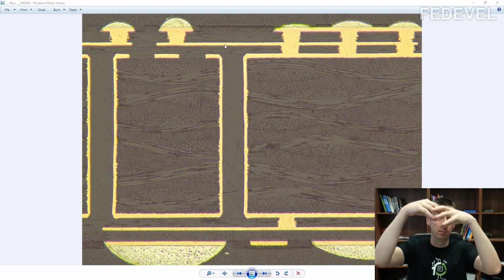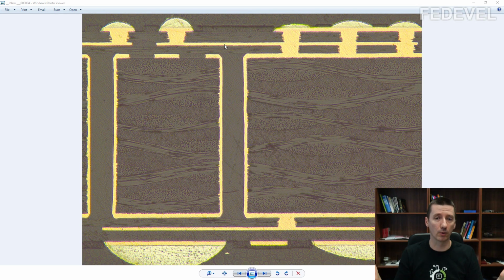It can damage the BGA ball and there will be no connection. Okay, so we really don't want to have air trapped inside of vias. And it used to be a problem, so I was curious to know if it's still a problem, or what are Mike's thoughts about this kind of problem, air trapped inside of vias.